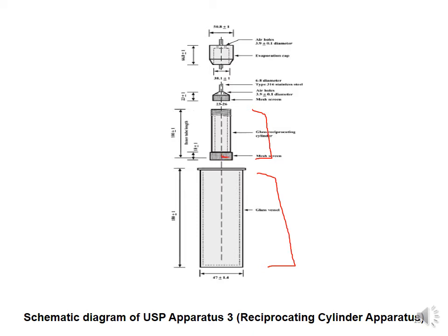Inert fittings and screens are made of suitable non-sorbing and non-reactive material and are designed to fit the tops and bottoms of the reciprocating cylinders, with a motor and drive assembly to reciprocate the cylinders vertically inside the vessels.